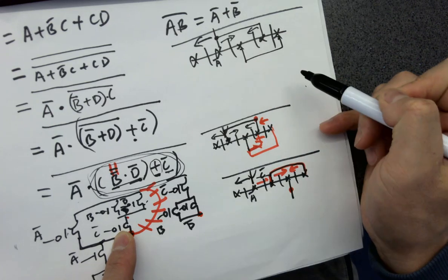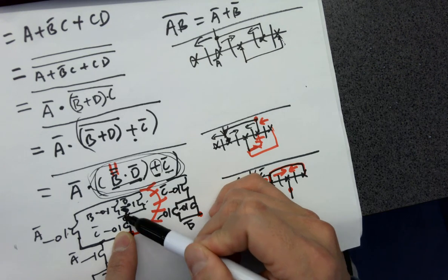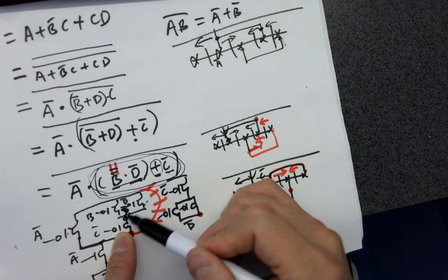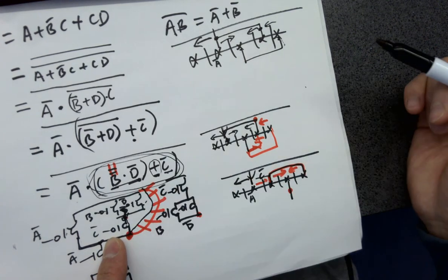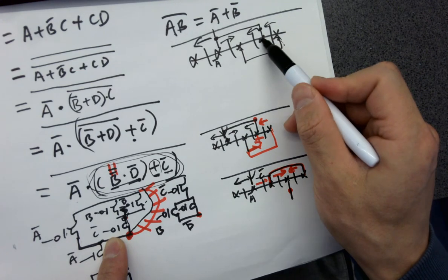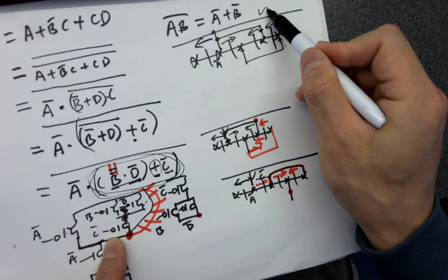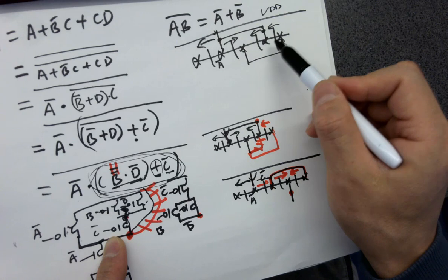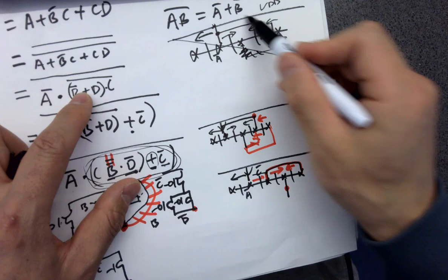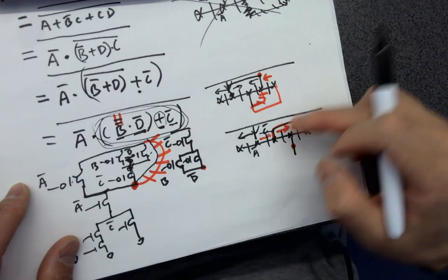Because if it goes this way, it means you are letting the current go through this channel and eventually merge at VDD. So it's basically going through here and going to VDD. Right? Because after this terminal, they are sharing a terminal over here, so eventually it goes up to VDD. So it becomes impossible. That's a problem. So this is not working. So I have to swap it and move it to the top. Just one single transistor on the top.